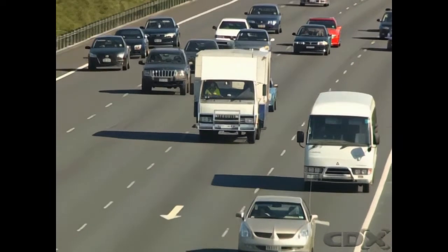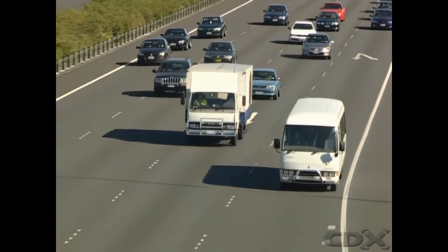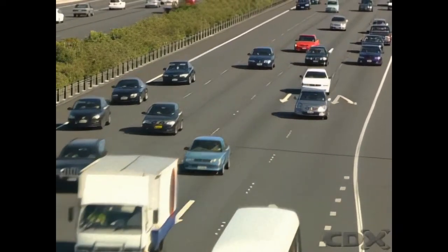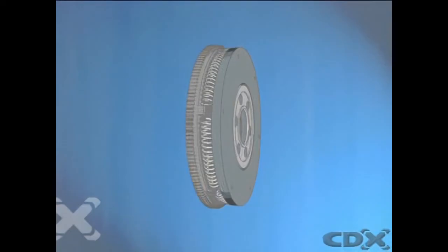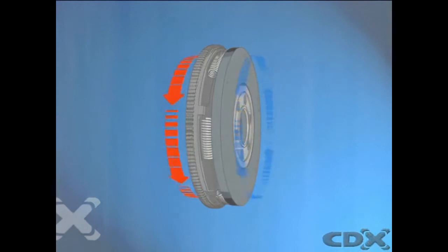This results in a strong torsional resonance or vibration that occurs during operation of the vehicle within normal driving ranges. The function of the dual mass flywheel is to isolate torsion crankshaft spikes created by diesel engines with high compression ratios. By eliminating the torsion spikes, the system eliminates any potential damage to the transmission gear teeth.